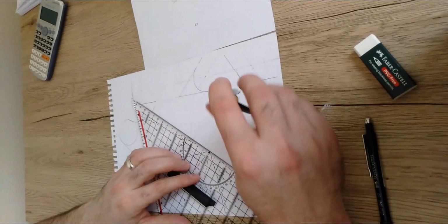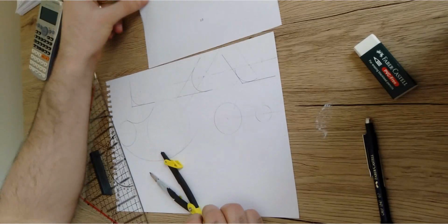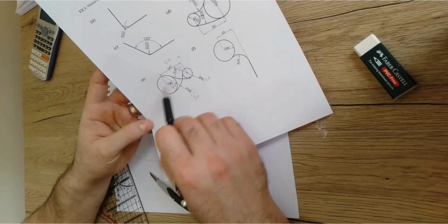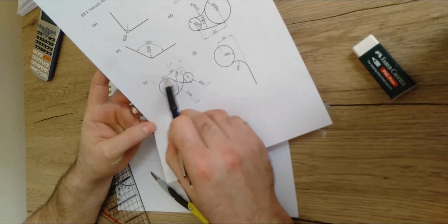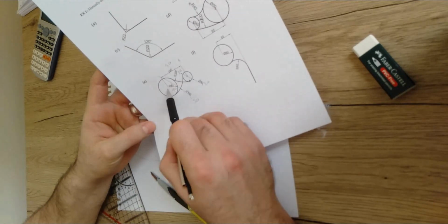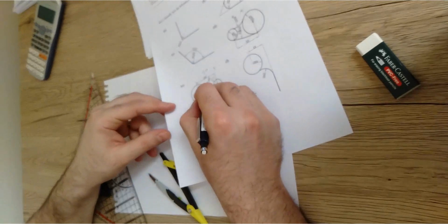This curve is going to give us the first locus to the center point of the small circle. Then I'm going to do the same for the second big circle. If I ask you to move from the center of this curve to the center of the big circle, are we going to go over the tangent point? Yes, we're going to go over the tangent point.